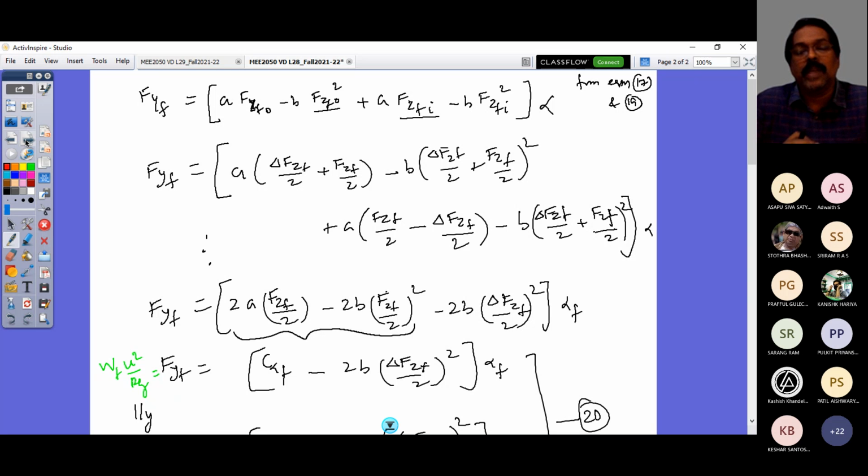We derived the expression for roll angle during steady state motion, and we derived what is called the roll rate, which is the rate of change of roll. It is change of roll as a function of lateral acceleration, not explicitly as a function of time. The roll change for the change in lateral acceleration is what defines roll rate.